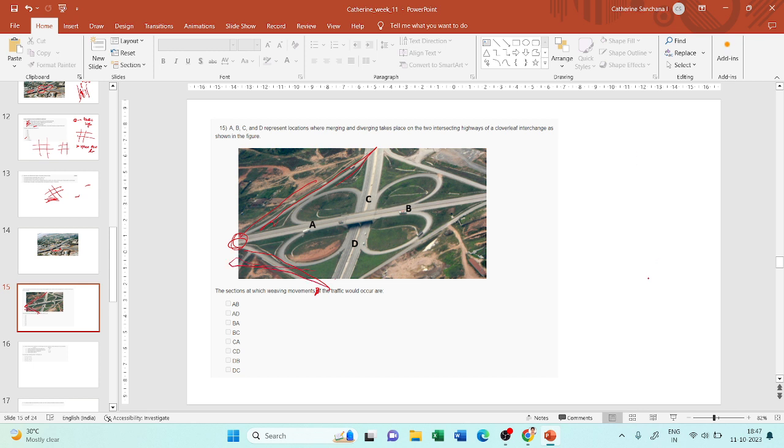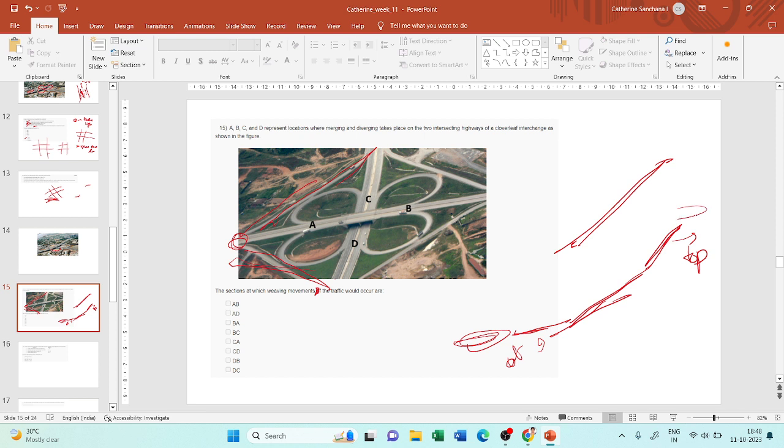So what can you infer from this? That a ramp is a road with a gradient, right? Since it connects roads at two different levels, it should have some gradient. Now what they say is the ramp will have a valley curve at the end, a tangent of constant slope in the middle, and a summit curve at the top. So this is the road at the lower level, this is the road at the higher level. At the upper end it will have a summit curve, at the lower end it will have a valley curve, and in between these two curves you will have a tangent grade.